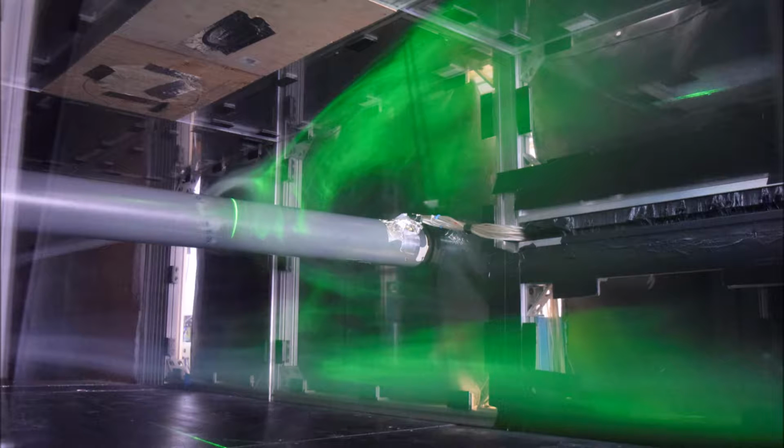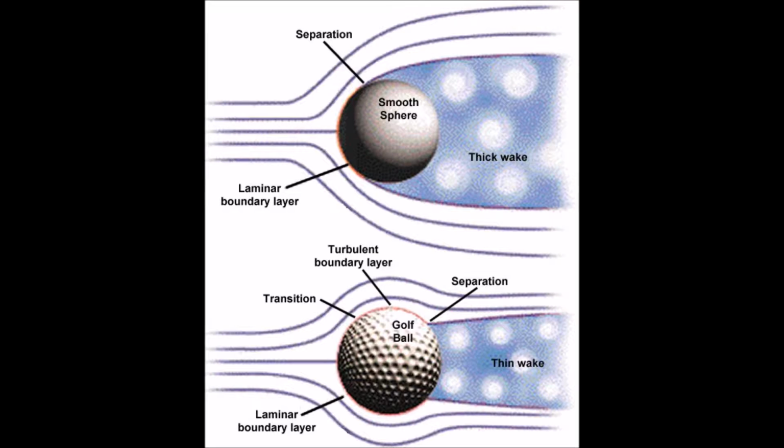Visual observations and pressure measurements were taken at two different Reynolds numbers, each produced by RPMs of 230 and 460. Flow was observed first over the smooth cylinder, and again with sandpaper on the cylinder to trip the flow and create a turbulent boundary layer, hopefully causing it to stick to the cylinder longer. After collocating the measured data and visual observations, it was clear that increasing the surface roughness of the cylinder created turbulence in the boundary layer and caused the air to stick to the cylinder for longer as it flowed around it. Through our experimentation, we are seeking to quantify the effect a turbulent boundary layer will have on drag.